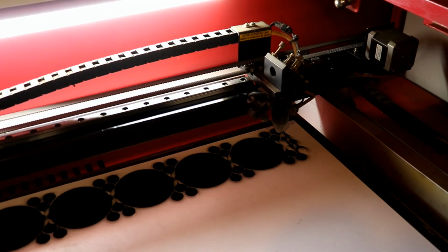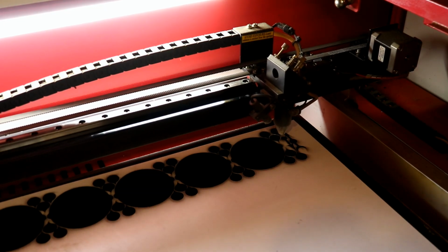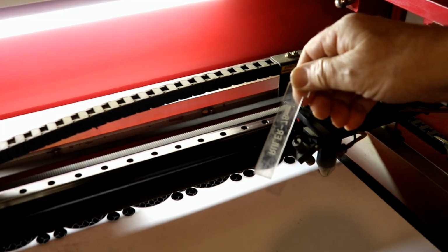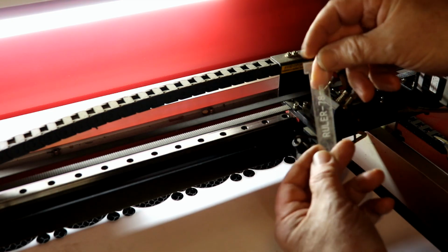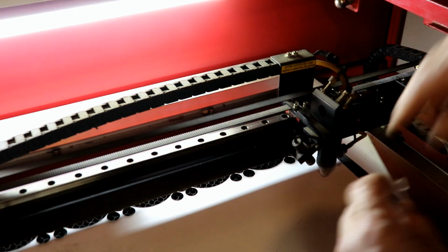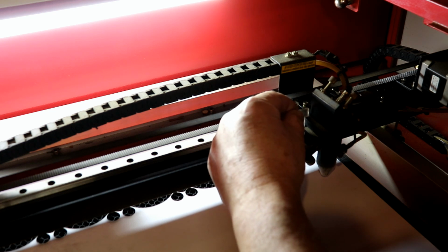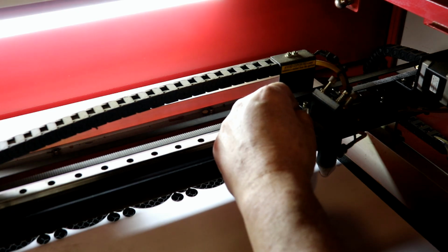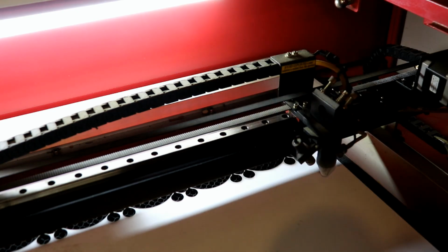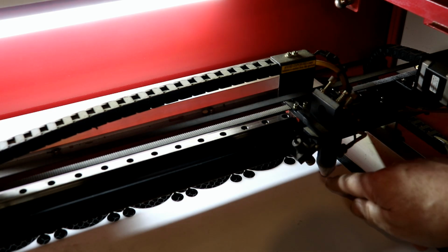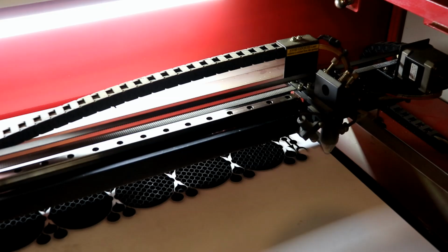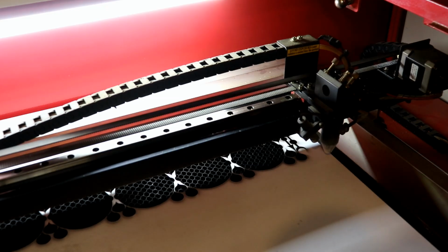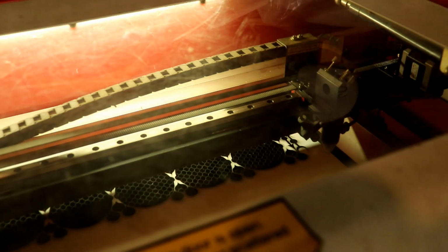Now what we need to do is to move the laser head over a fresh piece of material and use the focusing stick, which I've always used this ruler, 78 millimeters. You put it here, and then on this particular laser cutter, the whole of the bed where the material is sitting goes up and down. So you raise or lower that until it's perfectly focused. Then you can move the laser head back to a clear piece of the engraving laminate and shut the lid so it all goes nice and quiet.